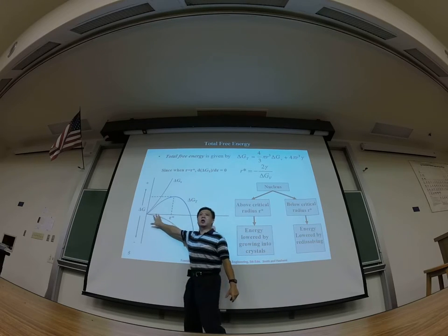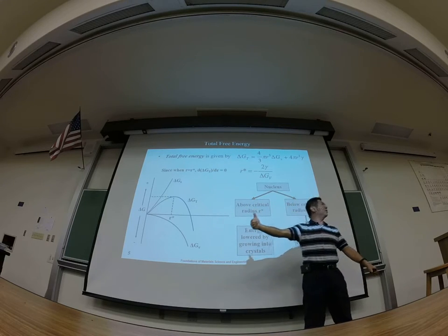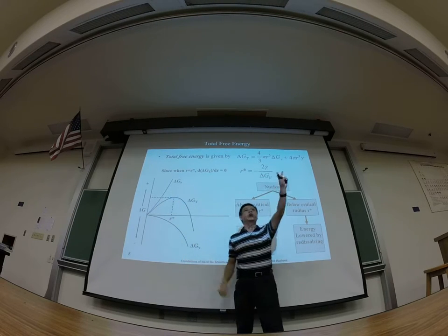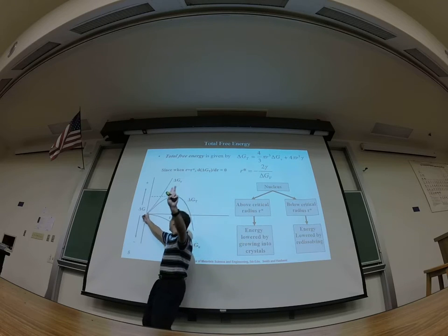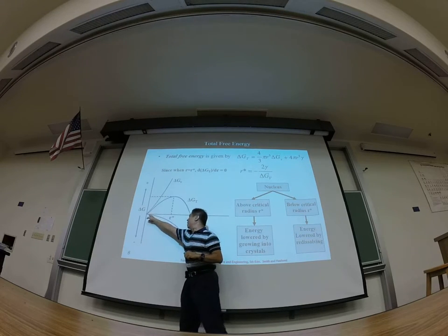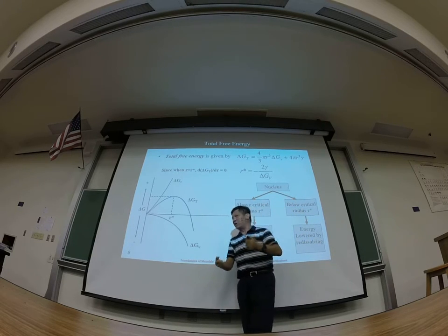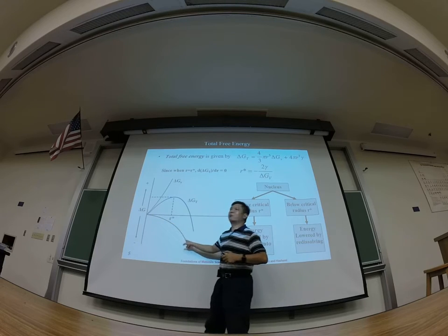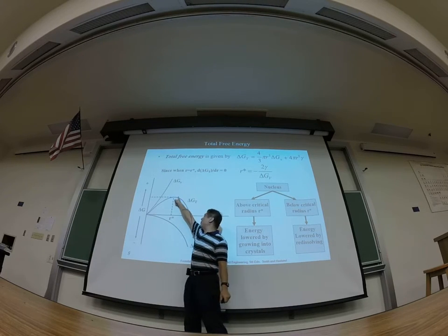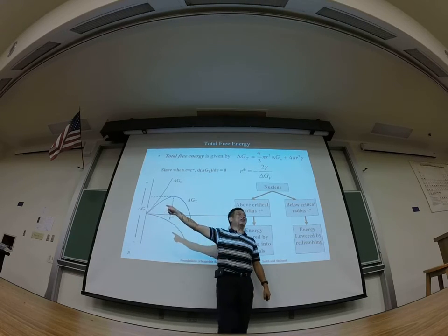So this kind of curve, I hope you understand, is very commonly used in chemical engineering and also in physics. When we consider the overall process, there are two contributions, right? One is related to the surface energy, which is always positive. Another one is the solidification caused by the phase change, which is an exothermic process, so it releases heat. When you combine those, you will see a curve like that. There's a maximum up there. This maximum corresponds to a size. We call that size the critical size.